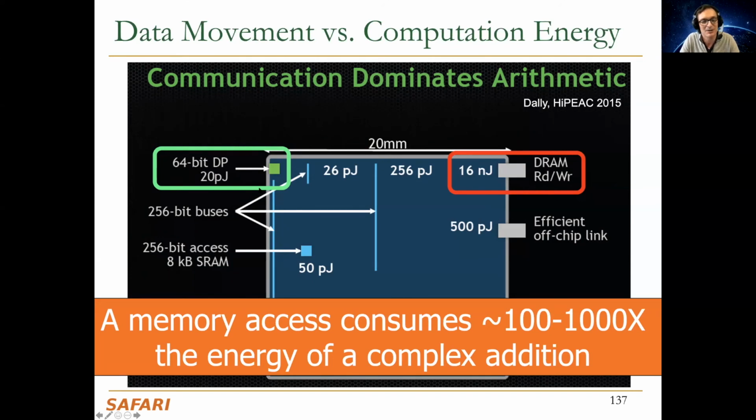So why did this happen over the course of 70, 80 years? The answer is technology scaling. We will talk about Gordon Moore and Moore's law. Moore's law and technology scaling, the ability to reduce the size of a logic gate and a transistor in CMOS technology, enabled us to reduce the size of that logic circuit, which reduces its latency, which also reduces its power consumption.